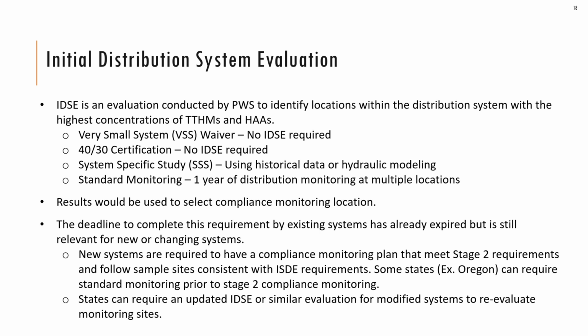So the deadline to complete an IDSE has already expired, so EPA does not require new systems or systems that modify their treatment systems to include disinfectants to complete an IDSE, but new systems are still required to complete a compliance monitoring plan that meets the Stage 2 requirements and follows sample collection sites consistent with the IDSE requirements.